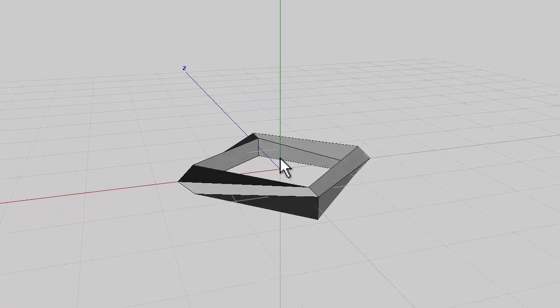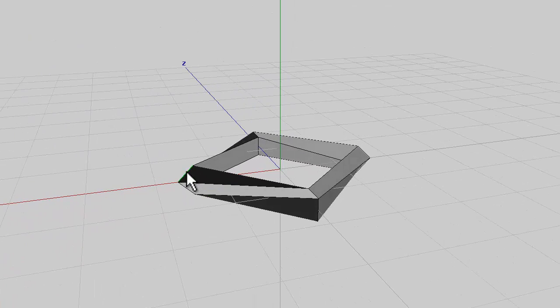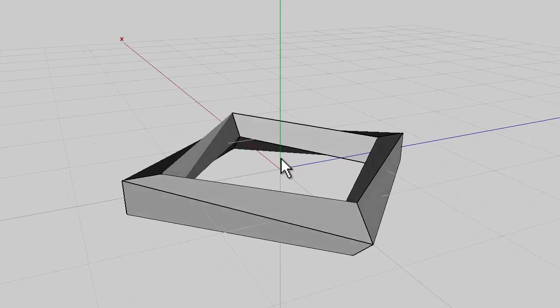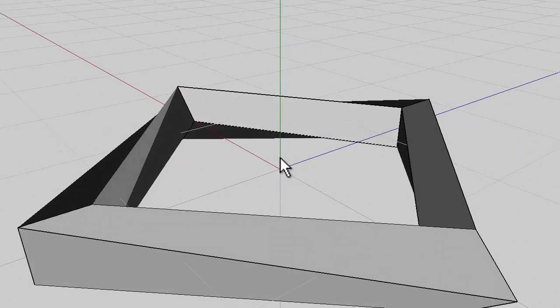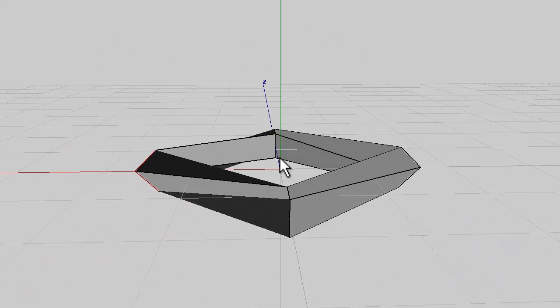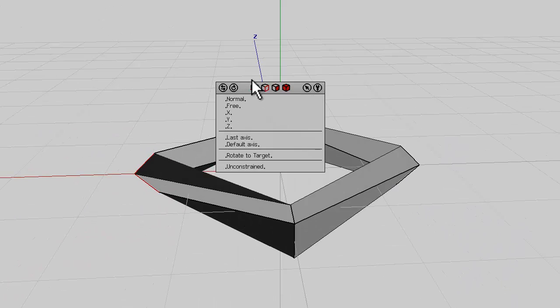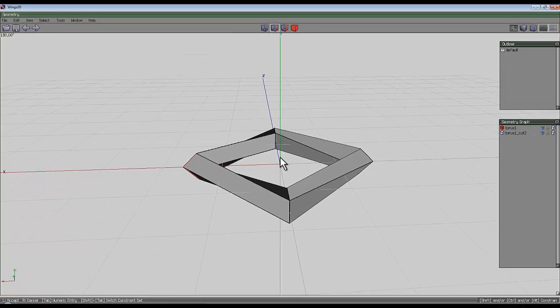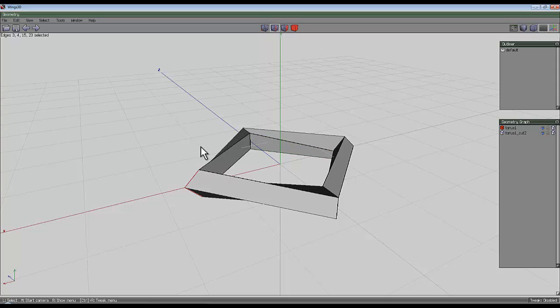Then still looking from this direction, it's important because we need the edges on this side of the cut. Select the 4 edges independently. You can't use loop anymore because it's no longer forming a loop because we've cut the shape. So we just need to select them from this direction, which is a little bit fiddly, and then once that's done, right click, rotate. It's going to be on Z, and then just check you can turn it over. Then use the shift key to do it in discrete steps. So that's 90, 180. That's given us our complete 180 degree shift round the entire shape.